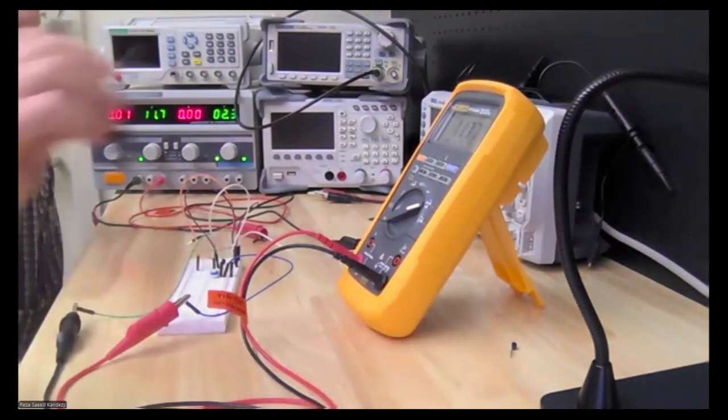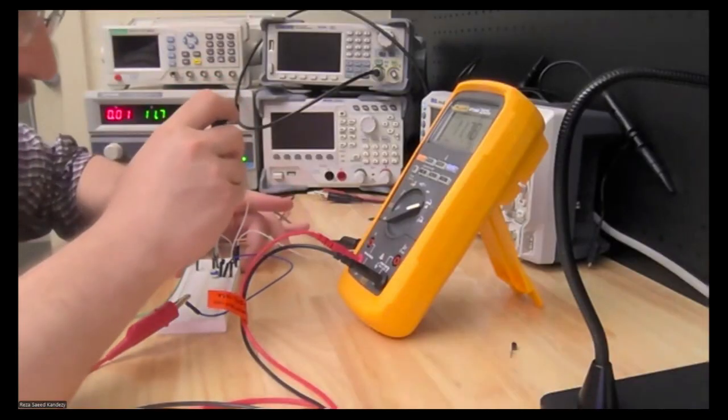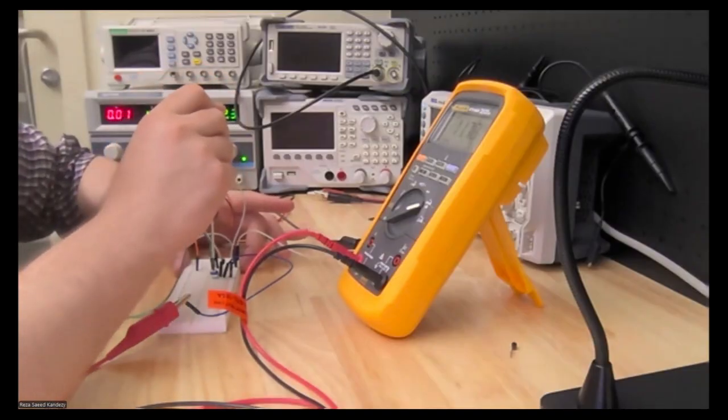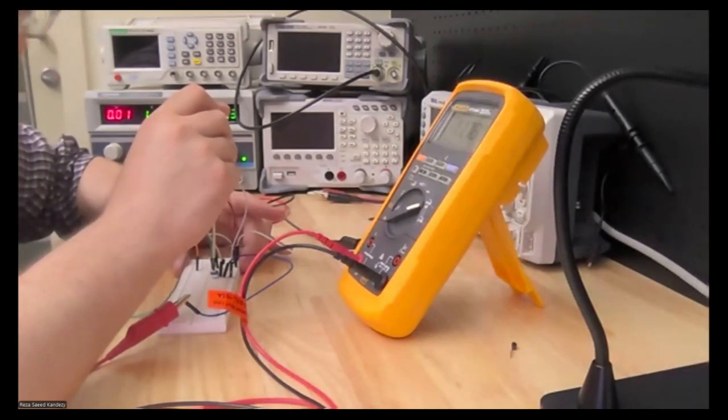Now, before we leave, I wanted to change the resistor. I use the potentiometer here. By changing the resistor, I am changing the voltage between collector and emitter, because the current should be constant. The collector current is a function of the current in the base, so changing the resistor should not affect the current of the collector. But by changing this resistor, I am changing the voltage division between the BJT and the resistor, meaning the voltage between the collector and emitter is changing.